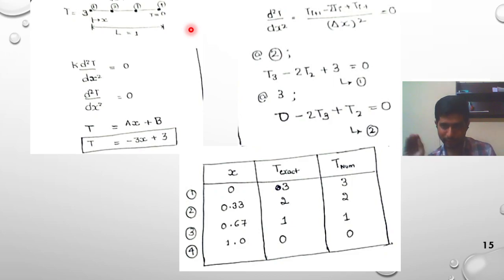Okay, so that is CFD. CFD is a finite resolution camera, which is the actual camera. An actual camera also has a finite resolution. So you can only capture the temperature values at 1, 2, 3, 4, and points 1 and 4 are boundaries, you already know. You are capturing temperature values at only 2 and 3. T2 and T3 is what I have written here. So T exact I can calculate anywhere. I am calculating it at x equal to 0.67. That is the third grid point.